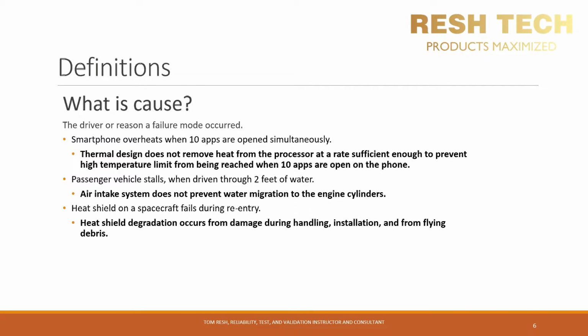A great example of this is in root cause analysis. The cause is the end result or the desired result of an investigation and analysis for a field or test failure. In the case of the smartphone, the cause was the result of a thermal design that was not sufficient enough for the amount of heat generated by the process, which causes the high temperature limit to activate and shut off the phone. A case like this could have been the result of an inexperienced thermal team, but more than likely was the result of a cost reduction either on the product company's side or on the supplier's side.